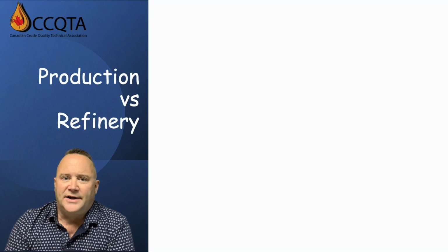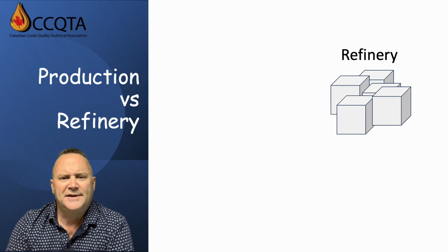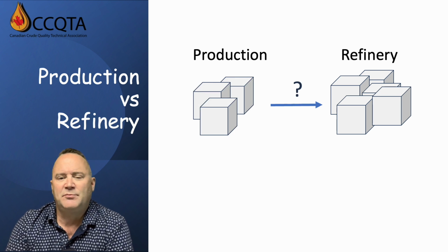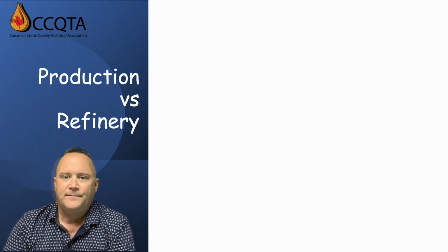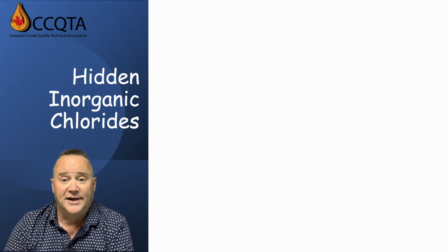In the early 1990s, a situation arose in a heavy crude where the measured salt content at the refineries was consistently higher than the levels reported at the production site, despite the fact that all locations employed the same conductivity test method. One of the receipt refineries was also experiencing severe crude unit corrosion problems. At that time, various theories proposing pipeline cross-contamination and/or the presence of organic chlorides were offered to explain the anomalies and plant corrosion problems.